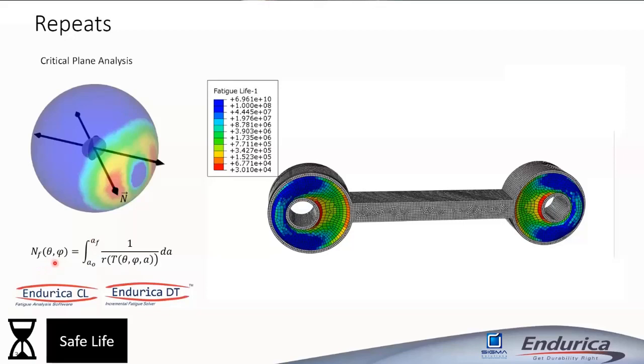One of the limitations of methods that are based on a Wöhler curve, right? The metals fatigue people sort of pioneered the use of these Wöhler curves for fatigue life prediction, but for rubber, Wöhler curves are very problematic. One of the problems is that they assume that the fatigue life is predicted by the maximum principal stress, which is true in certain cases, but it's certainly not always true. In simple compression, that breaks down. When you have a strain crystallizing material, that breaks down. Critical plane analysis is the method that allows you to correctly predict those effects.